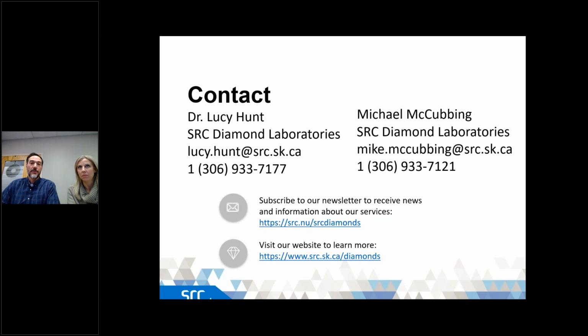So what you also want to do is calibrate that unit to make sure that you've got that density threshold somewhere in the middle of the region between the predominant bulk material and where the diamonds lie, to then manage your yields and get to an efficient cut point. The nice thing is diamonds are that technically boring chemistry where they are pure carbon. You do get hydrocarbons or pieces of plastic that will get picked up, but those can be removed with alternative methods other than XRT.